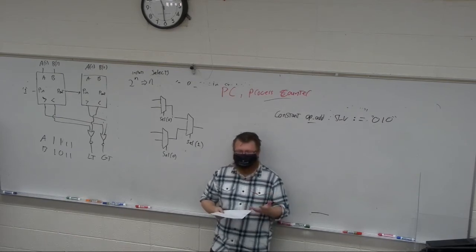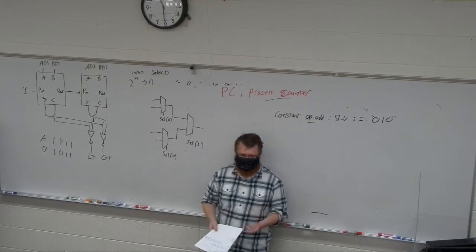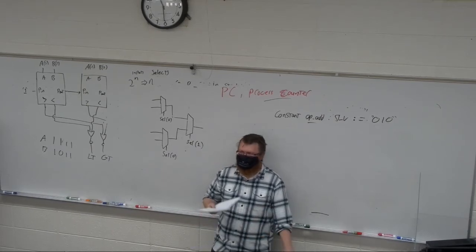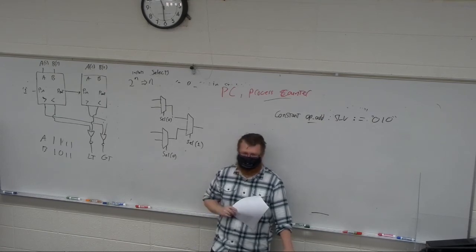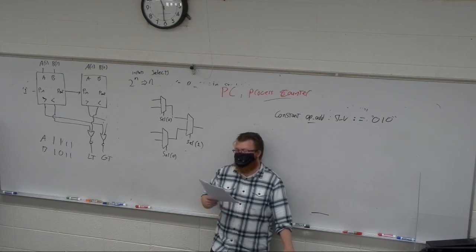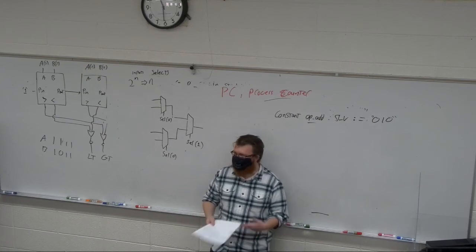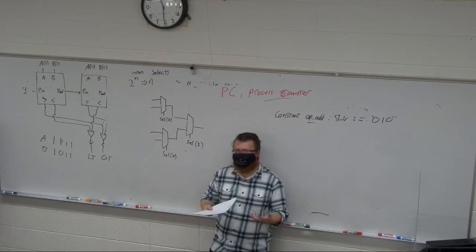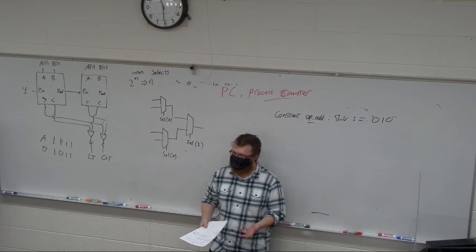But number 5 on homework 12 is really interesting because it asks you to create a shifter using nothing but 4-to-1 multiplexers. I'm not going to post the code to that because that's not really the important part; I believe that you can write the code once you have the architecture of the circuit.